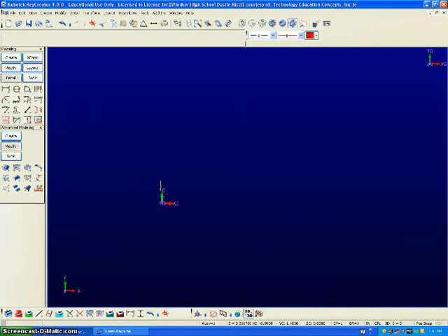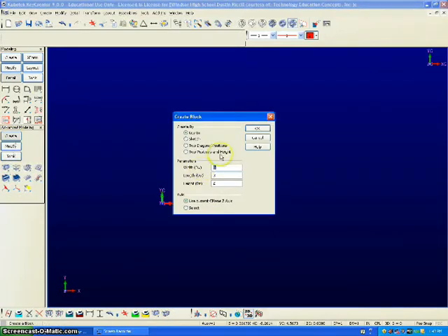In this video, I'm going to be demonstrating how to use primitive solids on Kubotek Key Creator. I'm going to be demonstrating this by creating a modified slide block using the create block and cylinder tools, in addition to trim solid curves and a little bit of create solid blends. So we're going to start out by creating a 6x3x2 block